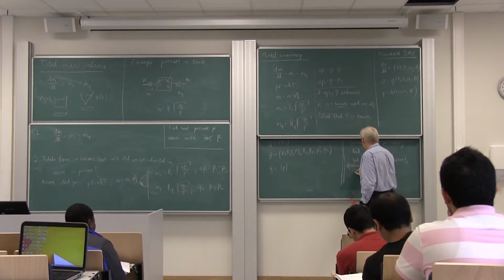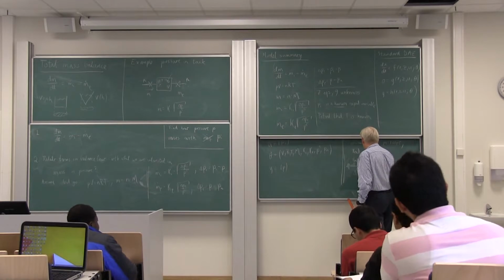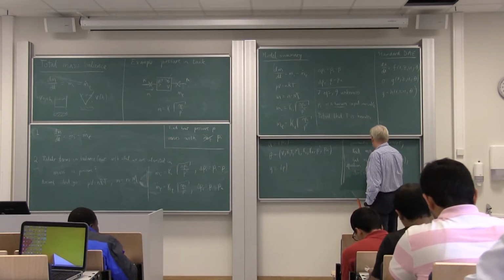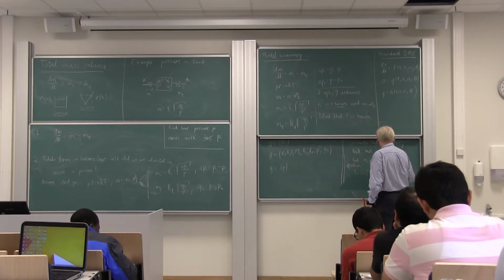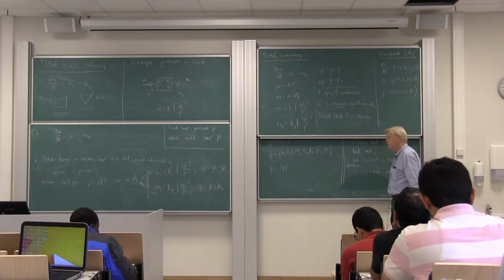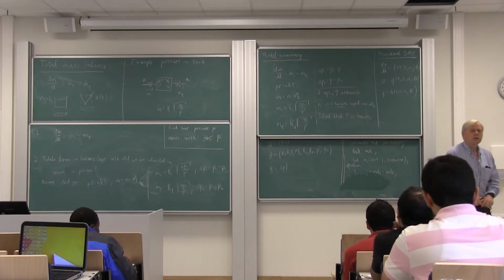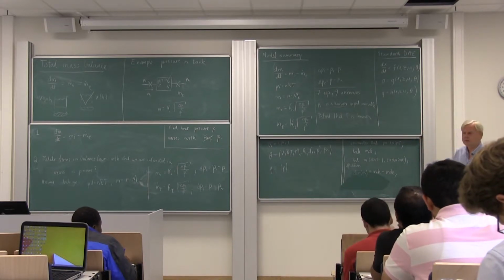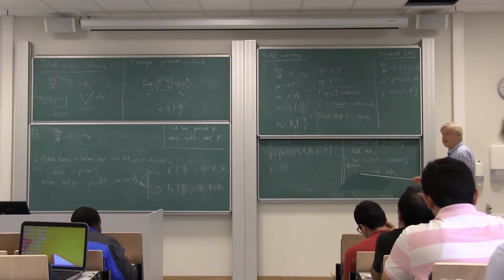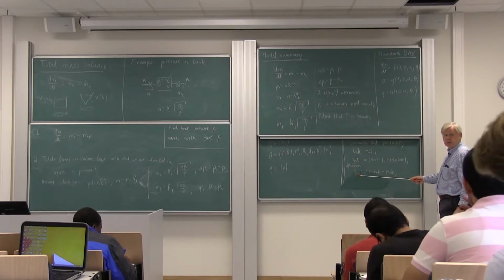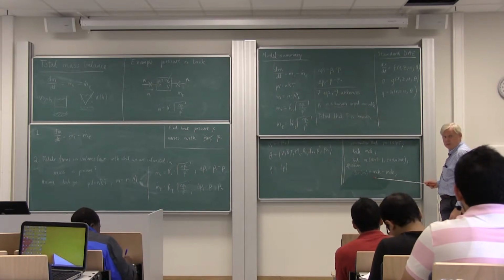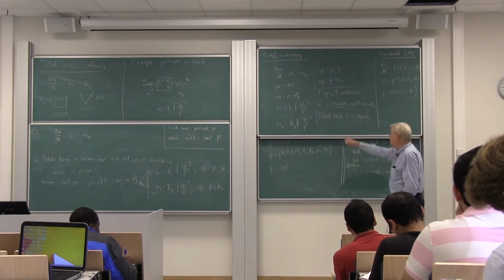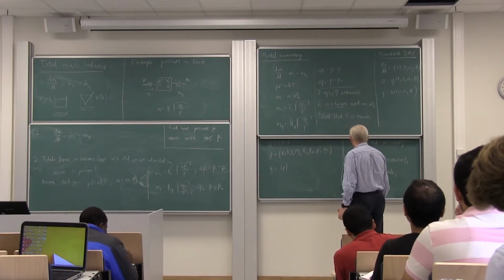That would be der(m) = mdi - mde; and here you observe that Modelica supports an operator or function der, which means time derivative. So this means the time derivative of m equals mdi minus mde. And then pV = nRT.